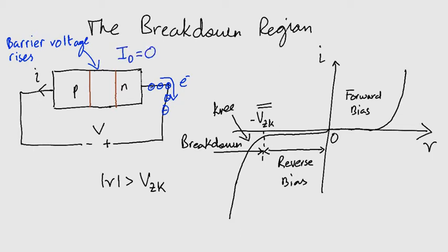However, unlike the reverse bias case where the depletion region stops getting wider, we continue to pump more electrons out of the N region, further increasing the width of the depletion region. This is the breakdown. This continues until a high junction voltage appears and a new mechanism is needed to continue supplying the reverse current. One of two breakdown mechanisms comes into action.